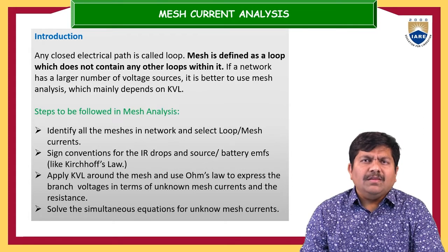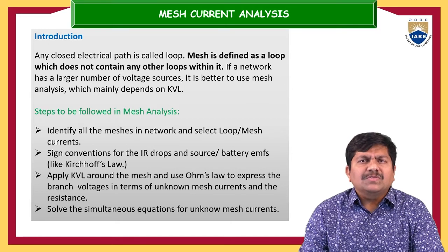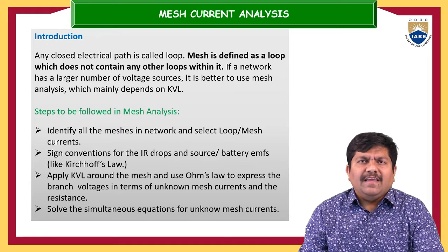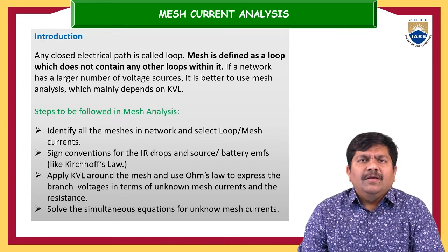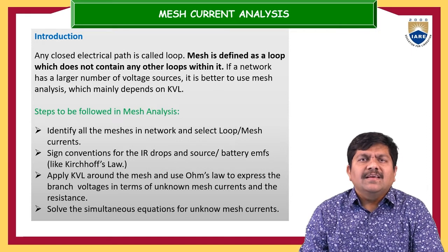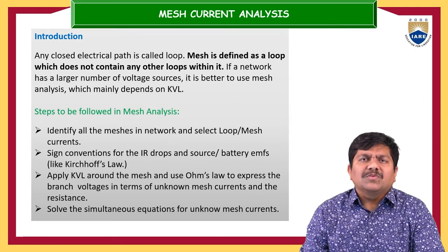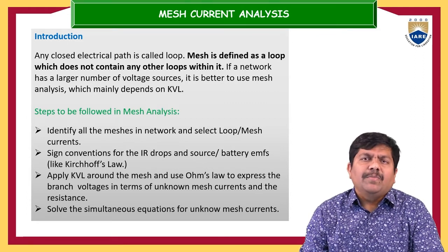Based on our objective, if we want to determine the current, then every voltage source can be brought to a current source with the help of the source transformation technique. This is highly helpful if we find a combination of different sources in the given electrical network. But if the circuit consists of purely a larger number of voltage sources, then mesh analysis is preferable. If it consists of more current sources, then nodal analysis is preferable.